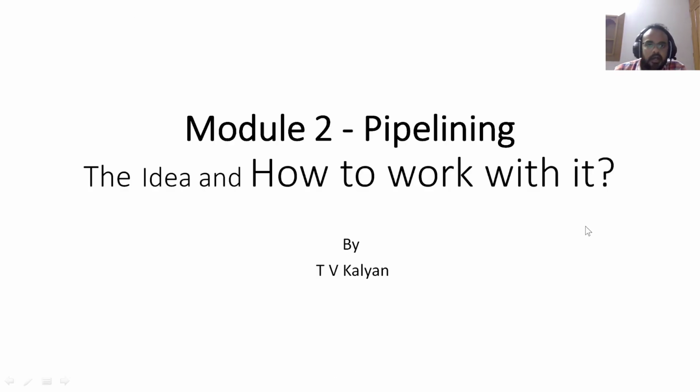Hello students. So far in module 2, what we have seen is how we have split the instruction execution into 5 distinct steps. One to name: fetch, decode, execute, memory, and write back. After that, we started building the control path and data path, basically at the block level, maybe not at the actual circuit level, because that's where our abstraction is in this course.